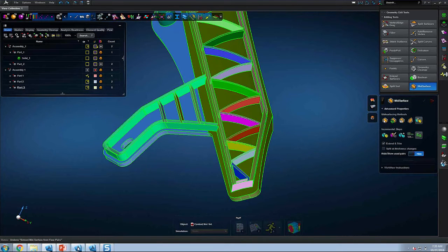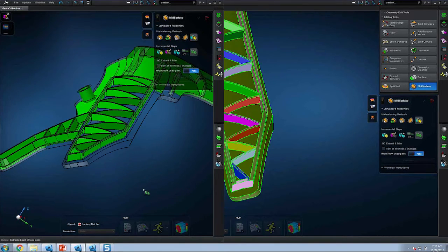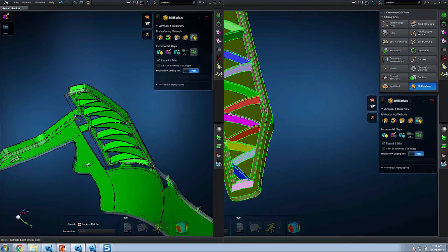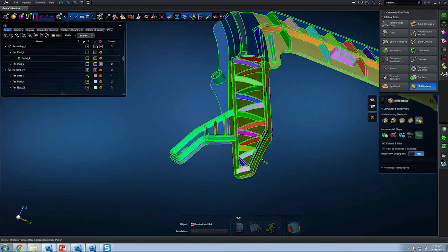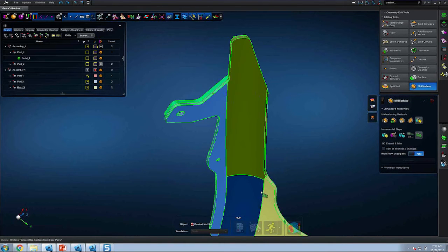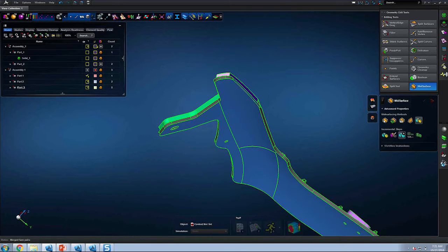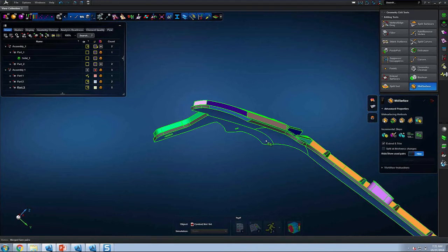And again, I'll be using this other model as reference, so let's go ahead and zoom out here on the left. I noticed that there is an entire missing section here. What I can do at this moment is merge these green, blue, dark blue, and light beige colors together. This will let me later extract one nice, large, continuous midsurface here. So let's go ahead and merge these two together. Let's actually go ahead and extract the midsurface and see what that looks like.